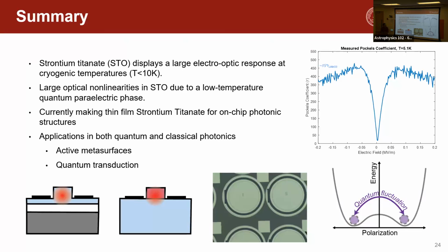The main lag is dependent on basically how well you're applying bias to your system. But there's no hysteresis. There is no hysteresis in this scenario. Of course, if you get into a ferroelectric phase, then you would have hysteresis.